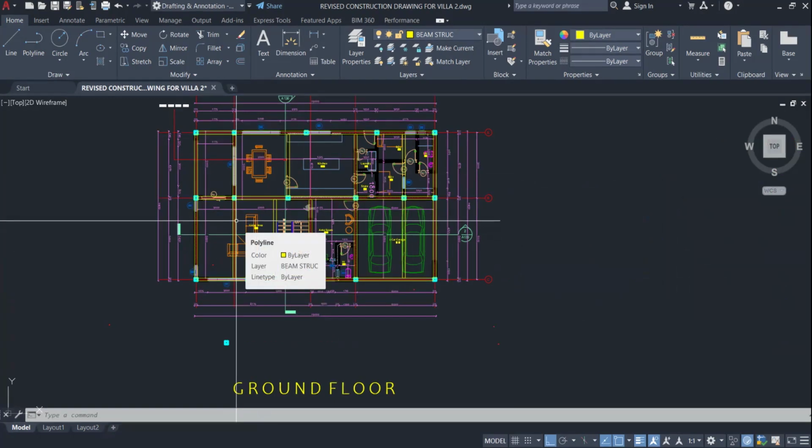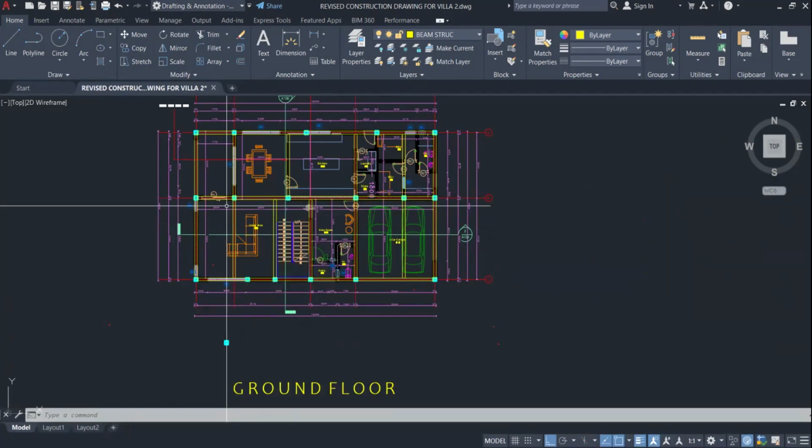I did not get you. What you are saying is, if the panel is too wide, then you don't want to introduce a beam, maybe in terms of designing for, let's say, a mosque or a very open space. In that kind of situation, most of the time, for example, if you are designing for a shopping mall, there's no way you can hide the beams. You can go to any shopping mall and just look around. You will see beams. But if you want a strict design where you don't want to see any columns, any beam, it is not a problem.